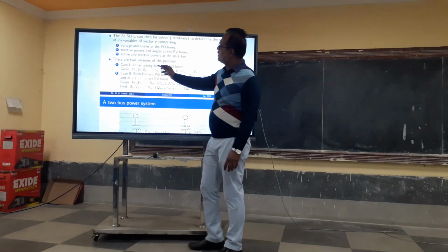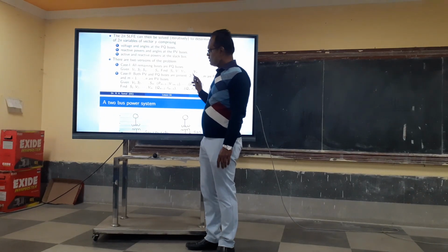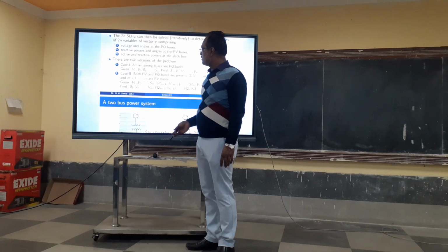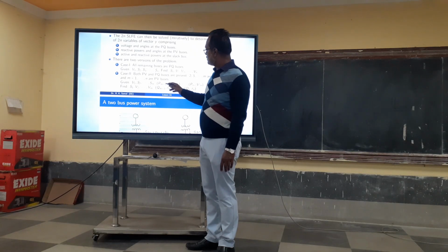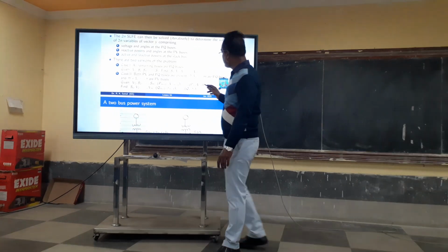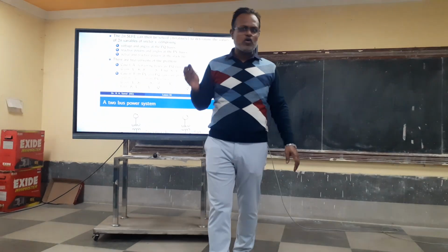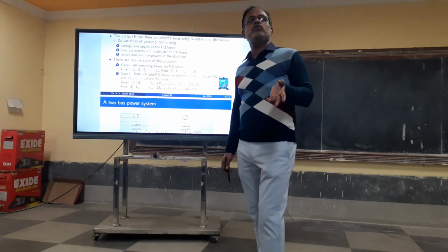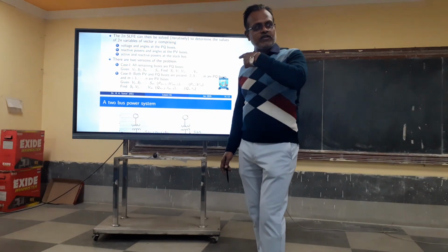Here it is given in case 1 what the known variables are and what we need to find. In case 2, when both PV and PQ buses are there, these are given for PV buses, and for PV buses we need to find out this. Two different kinds of buses. Every algorithm has this option of distinguishing between PV and PQ buses. In MATPOWER, if you have downloaded it, go to the data folder. In that you will find the case files where all these things are specified.